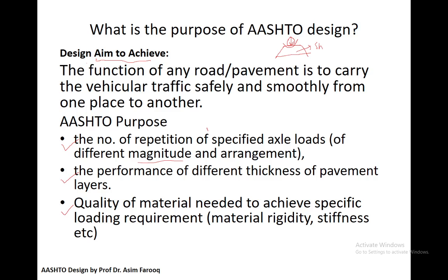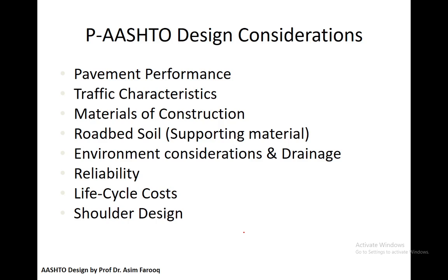The second purpose is to determine the different thicknesses of the pavement layers, and also to specify the quality of material through which we can achieve the specific loading condition, or the design life of the pavement, such as material rigidity and stiffness.